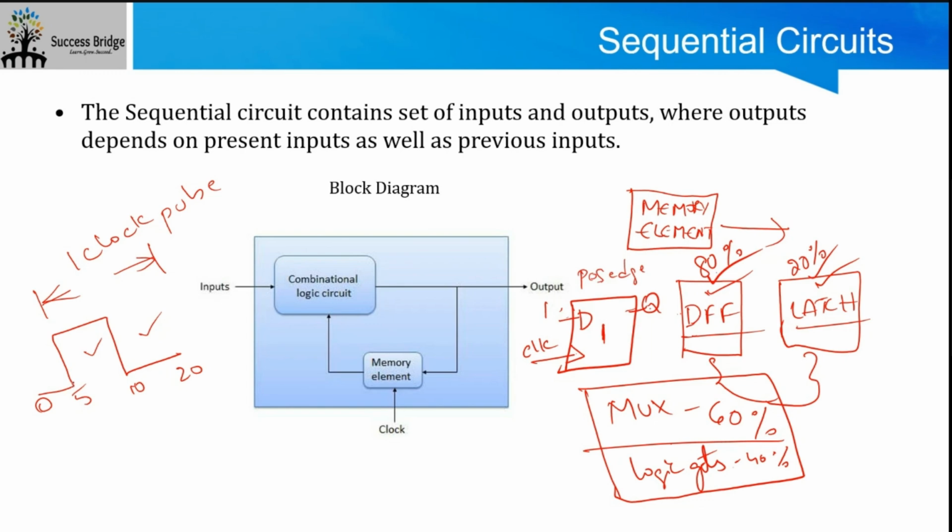That means when you're giving a clock, the data toggles at the active edge of the clock pulse. Okay. So on a complete one cycle, the value is stored and it comes to the Q. If there is a connectivity to another flip-flop, it reaches this particular flop input. It is not saved in here, it just reaches. Okay.